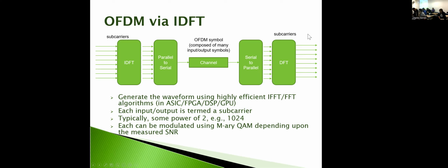And when we have a high SNR, we might use something like 64 QAM. But where we have a low SNR, we might have something like QPSK or just BPSK, right? So something that has much greater distance between the symbols. Remember that concept from before the midterm.